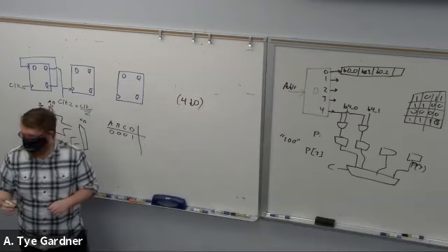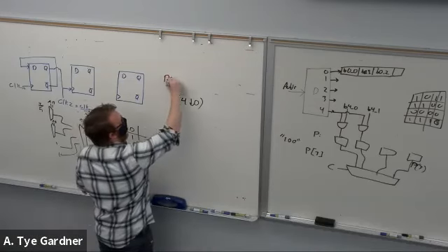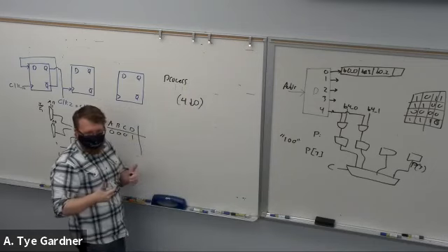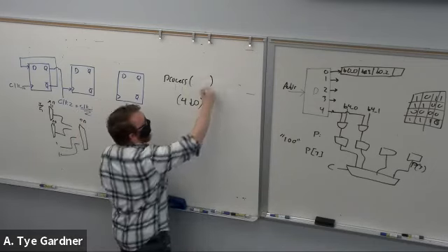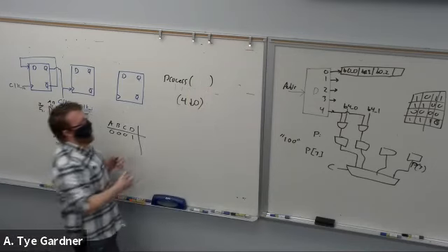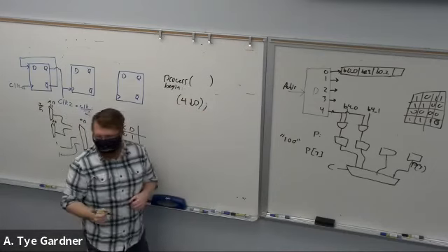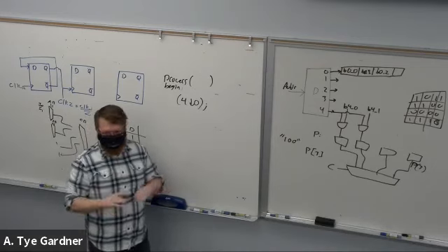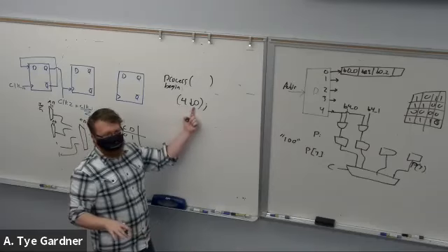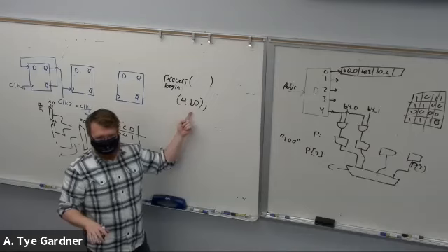is perfectly acceptable. The shorthand that I tend to use, again, if you write process and don't write the begin, I don't care. If you don't include the stuff in the sensitivity list, that's a problem, right? So things that are just syntax, so the begin, semicolons at the ends, that kind of thing, if they're forgotten, no issue. If the vector size is not declared or is wrong, that's an issue, right?